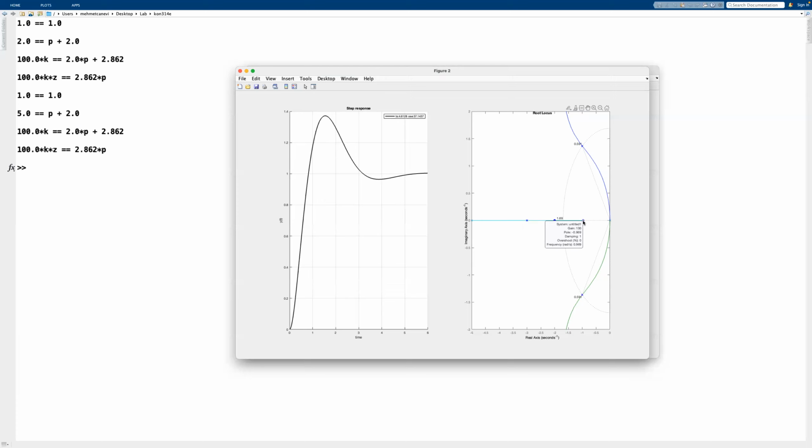But if it's a zero, it's even worse than adding a pole, because the overshoot became much, much higher then. Here it's not quite the same, because we have a pole and a zero in the dominant region, so it depends. Ideally, they should cancel each other out, or be far away on the left. Neither of those possibilities holds here, so this is not a good design.